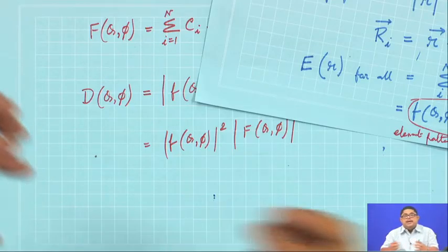Since they are very closely spaced, with spacing less than one wavelength for all array antennas, as we will prove later, there will be strong mutual coupling between them.